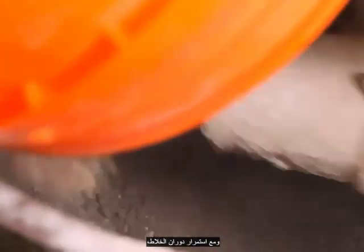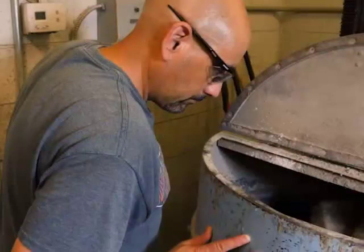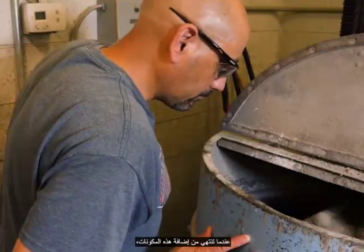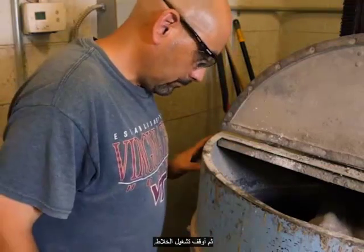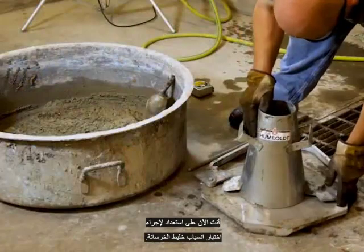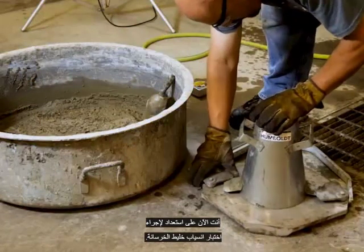With the mixer still rotating, add the cement and additional water in 5 to 10 small increments. When you have finished adding these components, let them mix for another 5 minutes and then turn the mixer off. You are now ready to test the slump of the concrete mix.